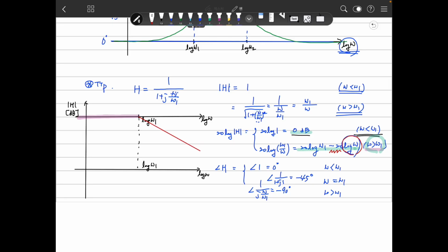So matching of that, the one dimension is maybe, if you say this is log 10 omega 1, and this is log 100 omega 1, then here is minus 20 and minus 40. That is minus 20 dB per decade. So this is the magnitude of this waveform here.